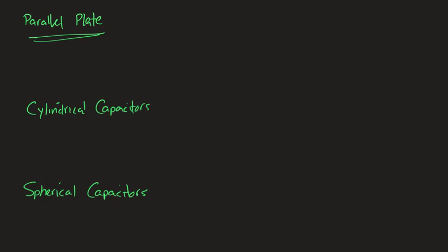But they would be too big to actually make capacitors. So generally, use a strip of metal, put another strip down, and roll them up. And that's what we have. So they're like a giant Swiss roll. And that is how almost all capacitors are made, which is why they all look like little cylinders. Because they are just two pieces of metal that have been rolled together. Now, to get smaller ones, we just put two little pads together and separate them with the material. But it's our responsibility right now to talk about how you figure out the capacitance of a set of materials.